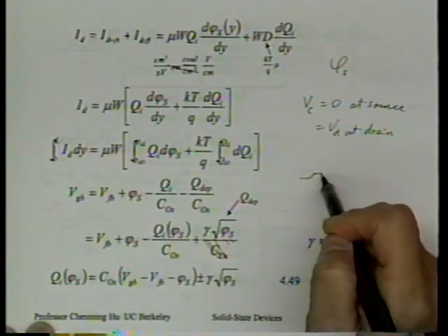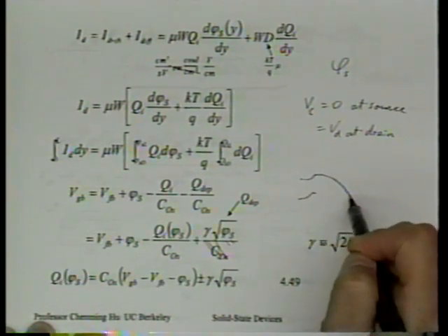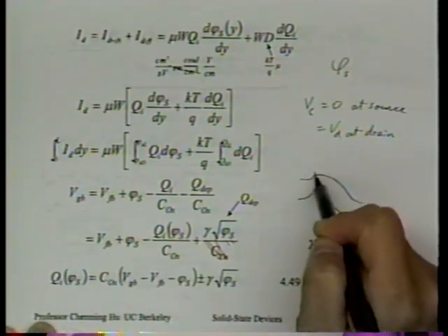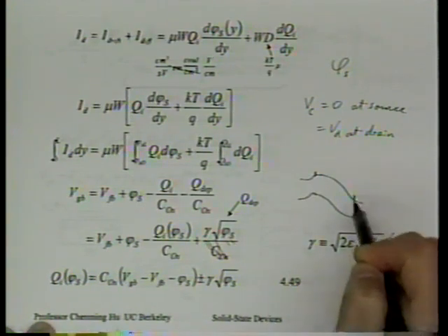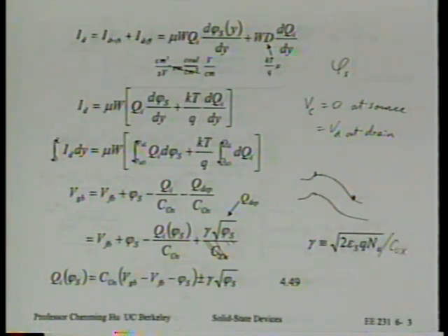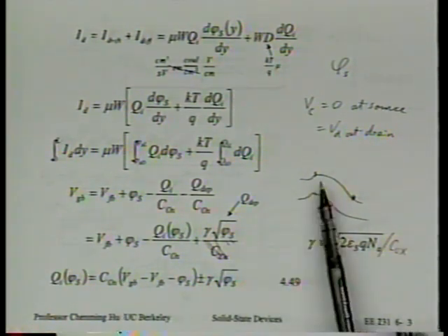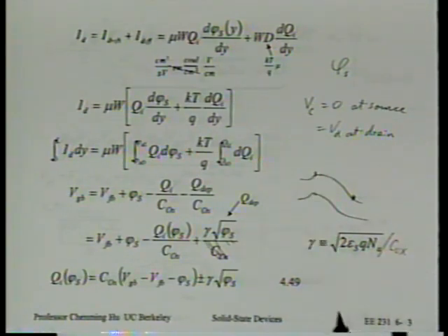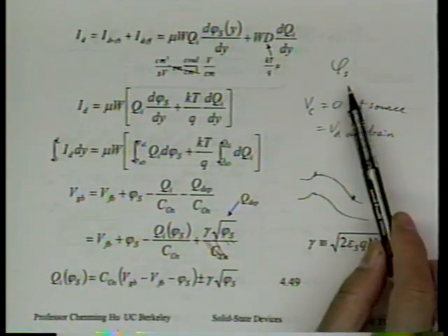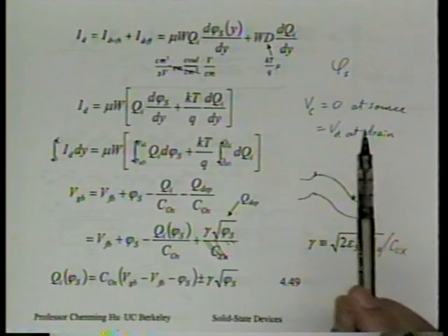We kind of ignore this little bit in this diagram, right? We'll call this VC equal to 0. We'll call this VC equal to VDS. Kind of makes sense if you think about the channel as a resistive sheet. Everything makes sense. But if you really look at the detail, it's a little difficult to define what VC is, other than VC is connected to source, therefore should be at the same potential as source. Phi s, however, there are no ifs and buts. It's exactly this point of phi s.